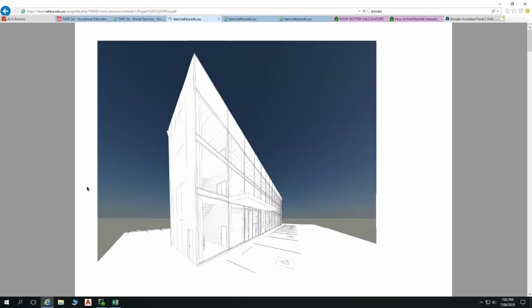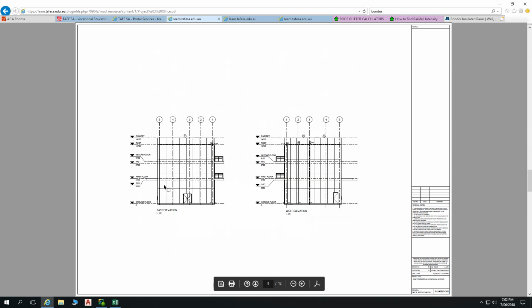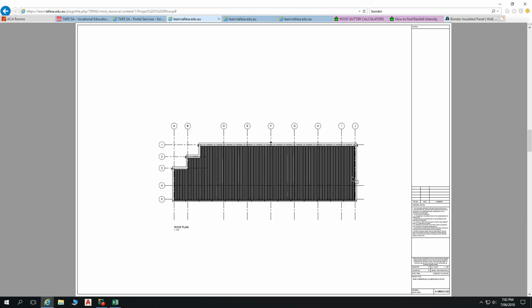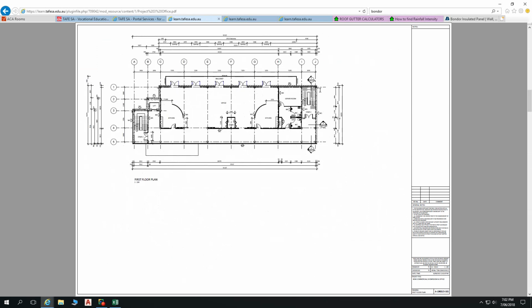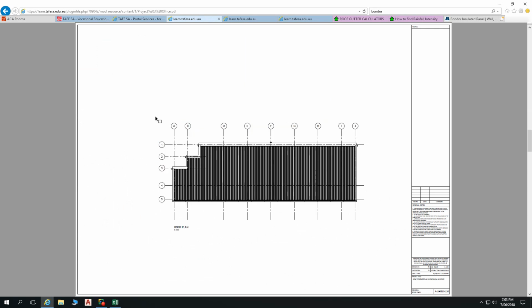So assignment 3 drawings. We have our roof there, but we can grab those dimensions from the floor plan, get the dimensions of our roof area, and basically we're dealing with the roof area of that shape and working out how many solar panels we can get onto that roof. One of the smart cookies in the other classroom suggested that the parapet wall provides 200 millimetres of shading at winter solstice.